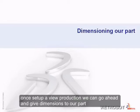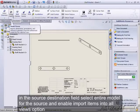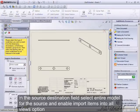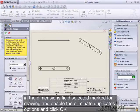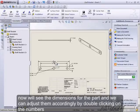Once we've set up our view projection, we can go ahead and give dimensions to our part. To do so, click on the Model Items button found in the Annotations tab. In the Source Destination field, select Entire Model for the source and enable Import Items into All Views option. In the Dimensions field, select Marked for Drawing and enable the Eliminate Duplicates option and click OK. Now we'll see the dimensions for our part, and we can adjust them accordingly by double-clicking on the numbers.